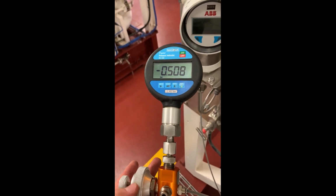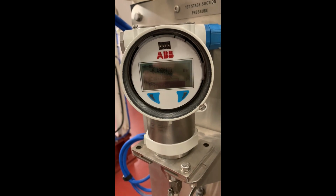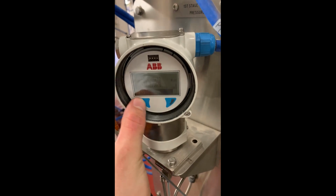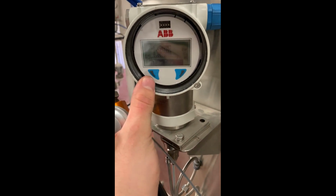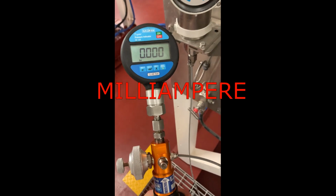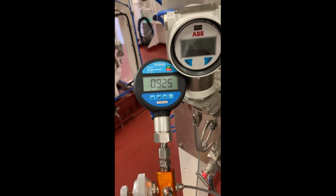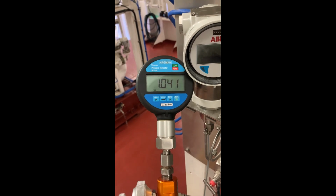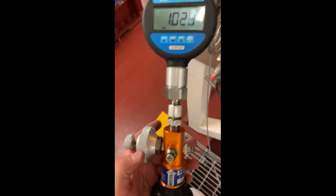We already connected our calibrator to the sensor, set our calibrator to vacuum mode, and create our auxiliary value, minus 500 millibar. Then push and hold the button which saves these parameters, which will be minus 500 millibar, and will be transmitted to Kongsberg as 4 milliamperes. Then in the same way make the span setting, which will be equal to 1 bar or the 20 milliampere signal.